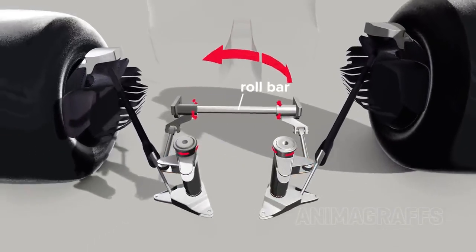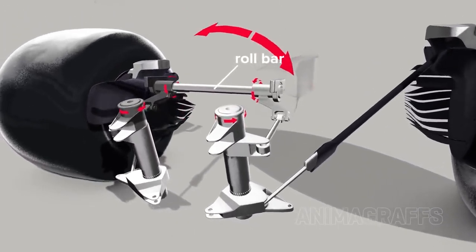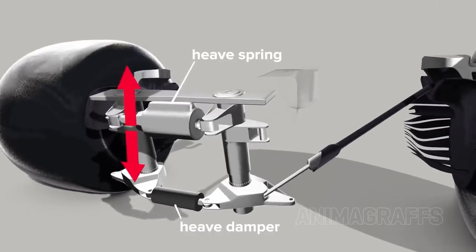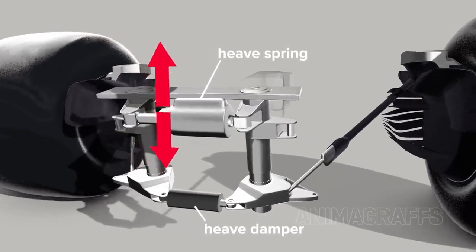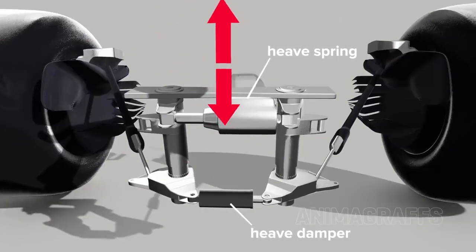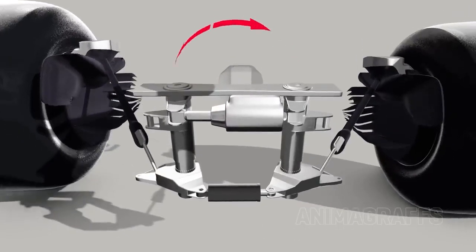Both independent suspension sides are linked to a central roll bar that twists to limit body roll. Heave is the vertical position of the car, which is critically important for proper aerodynamics. The heave spring and damper cleverly come into play when both sides move up or down together, for example, during acceleration or braking, but are mostly inactive for other movements.